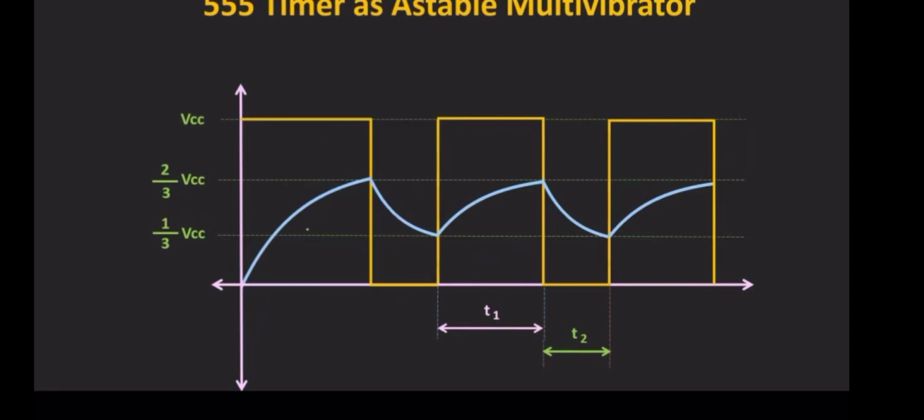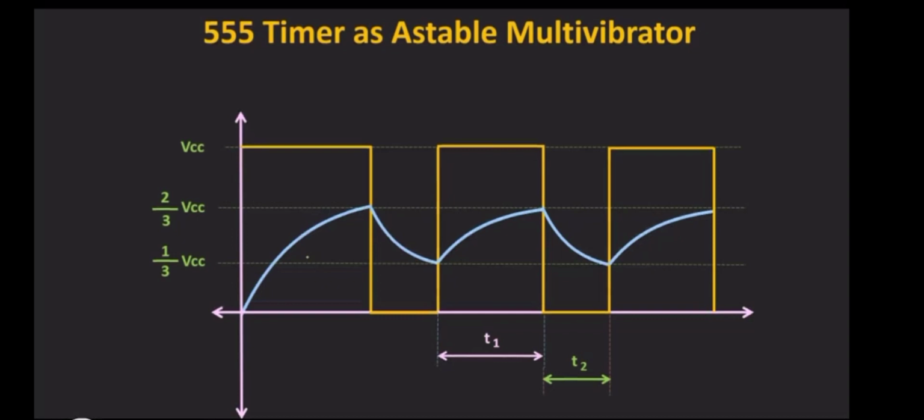So take down this waveform. So that is in case of a monostable multivibrator. So this charging time, it will discharge sharply, whereas in astable mode, it discharges at a certain time. So always T1 will be greater than T2. Charging time will be greater than discharging time.